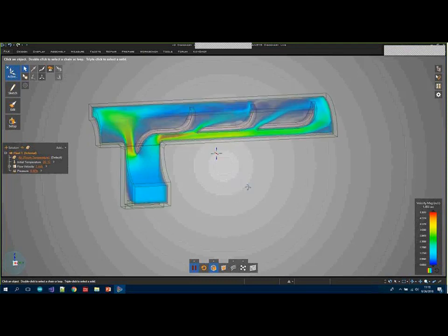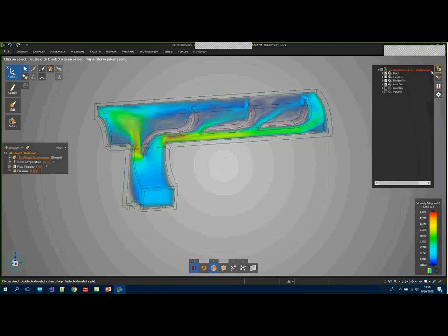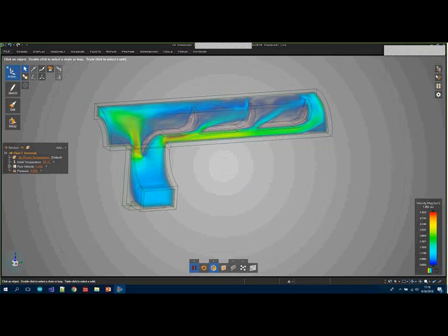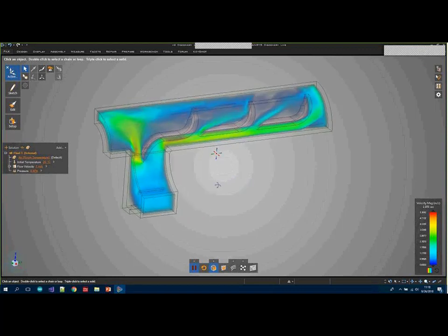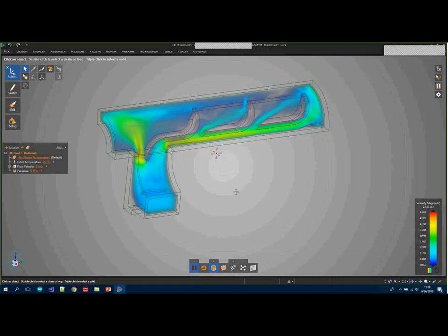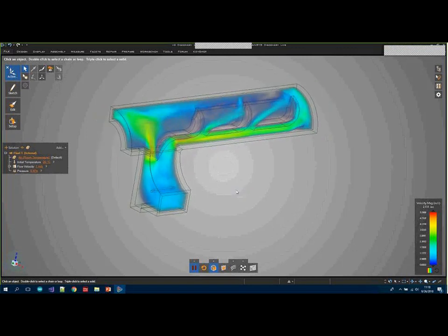So the last piece of this demo here is this heat bar. As I mentioned, you can insert items and temperatures to control or investigate how the flow will change based on a temperature. So this is important, if you have two fluids mixing together, or for instance a heater like this, you want to know, okay, is the heater at some temperature going to be sufficient to get the flow of the fluid to the desired temperature?